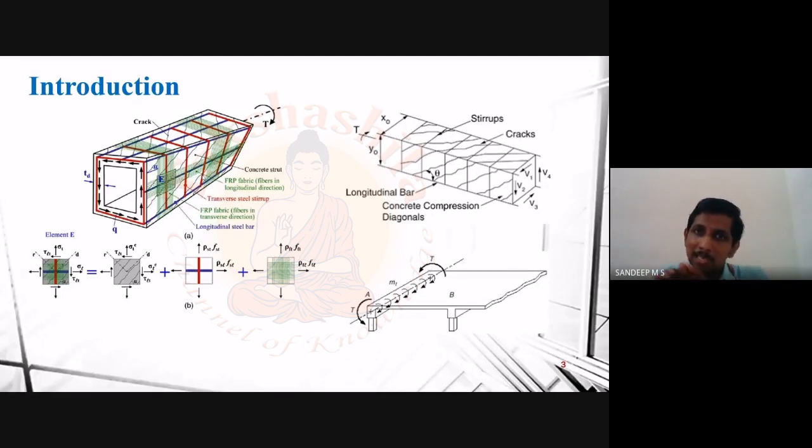that initially the concrete will try to take this tension at the maximum, but at the maximum stage the concrete will tell the steel that, see, I failed, I have done my part, now it is your turn. So once that value is exceeded, this steel will come into the picture and it will take up the additional tension so that it will be safe. This crack formation can be prevented. So that is how these reinforcements and the concrete play their roles. Okay, please understand that. So this is how you can prevent that.